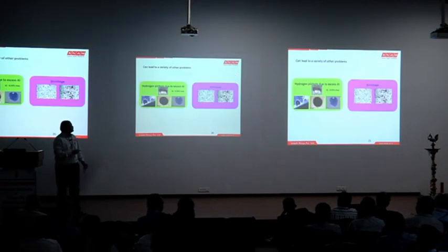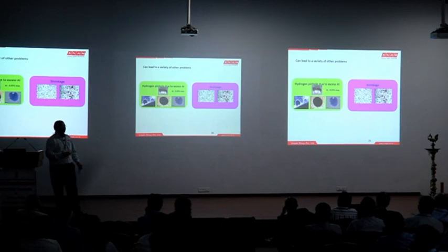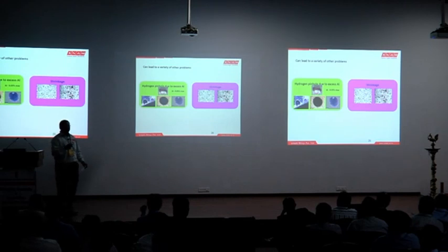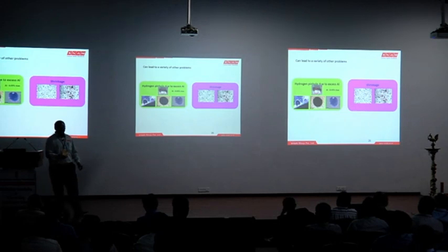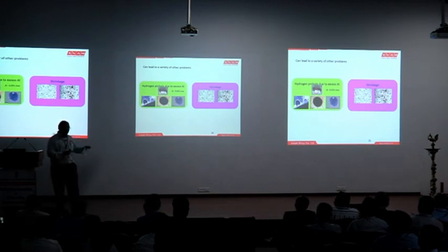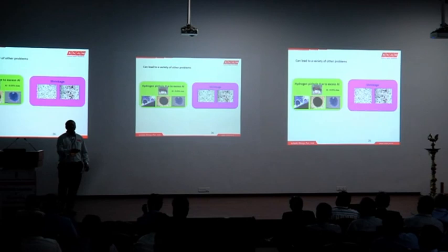Hydrogen pinhole tendency, aluminium. Actually aluminium you can call a catalyst. That does not mean increasing aluminium will give you pinhole. When you have surroundings with high moisture and a lot of gases coming from the mold and the liquid metal, and less permeability, in that case when high aluminium is present, then it can lead to a pinhole. We even have a variety of inoculant which contains 4%, 5% aluminium, which is successfully being used in manufacture of gray and ductile castings. So it is not high aluminium itself, it is the environment around, and the presence of high aluminium can create pinholes, or I should call it, aggravate the severity of pinhole.